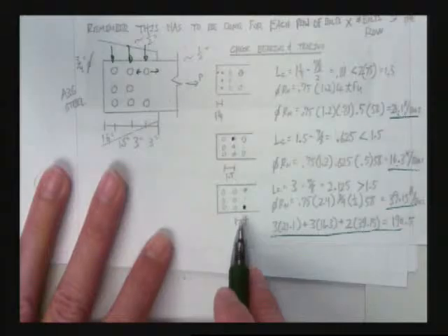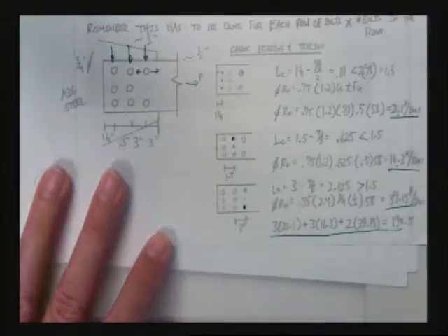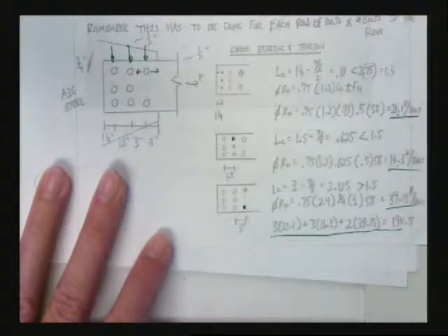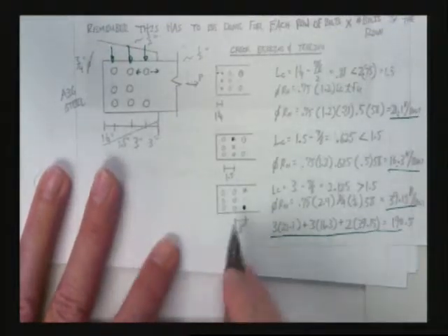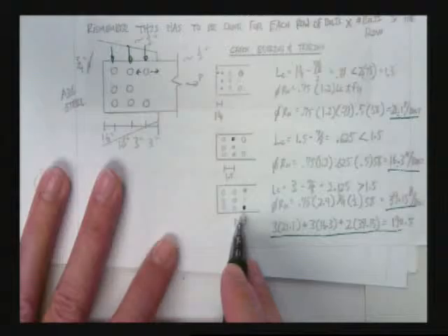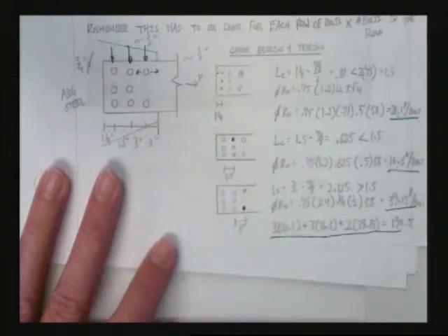No. Even your thought that one row could fail by itself is wrong, because structural resiliency tells us that if one row gets close to failure, the other ones are going to start helping out more, right? And they're not going to fail until they're all at their limit. Does that make sense? Okay.